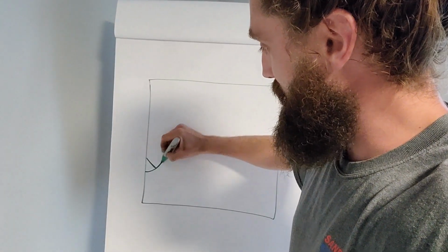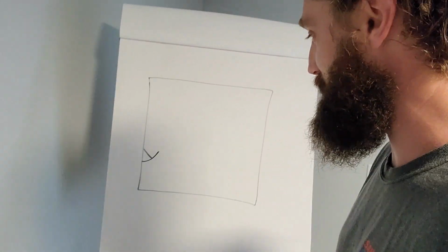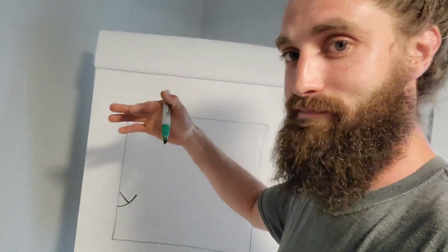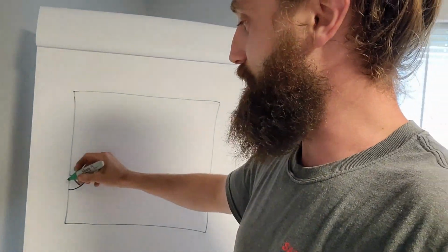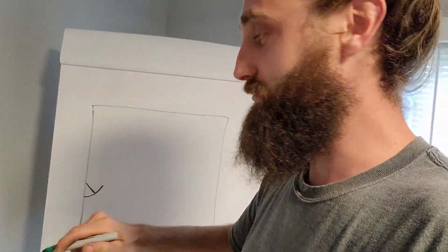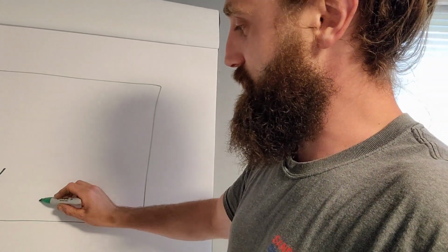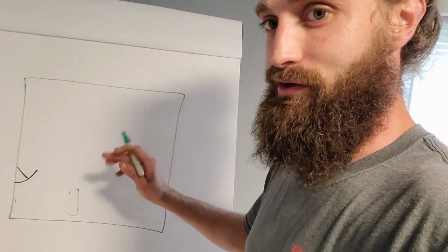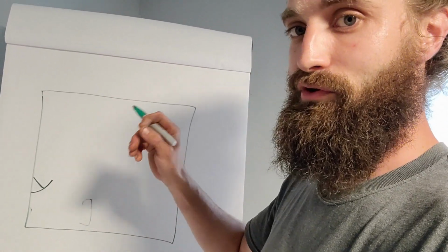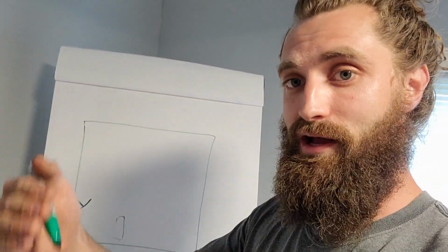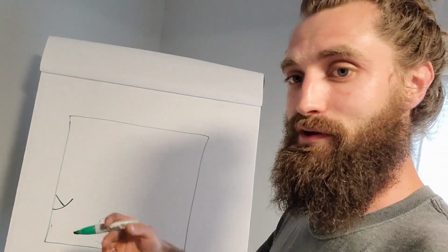All right, so we're getting our apartment laid out on the paperwork, and we're just going to start laying out components that we know are here. Things like windows, front doors, very common items, walls. You want to get all this stuff just laid out. Like I said, it doesn't have to be to scale, but as long as we at least get it on the paper. Unless you have an oddball door, we know what front doors are. They're pretty much a standard 6'8" tall, 34, 36 inch wide, stuff like that.